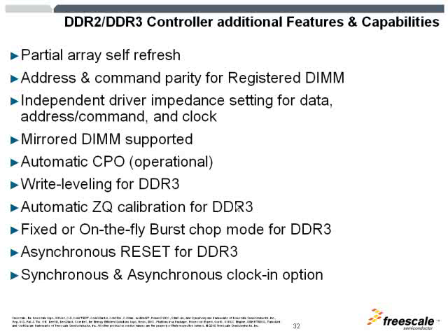This feature is very useful because as the voltage signals are lowering and as your timings are shrinking, you would need to rely on a very good and trustworthy calibration method. This method is initialized during initialization, and our controller is capable of providing the commands to set the DRAMs into modes that they calibrate themselves.